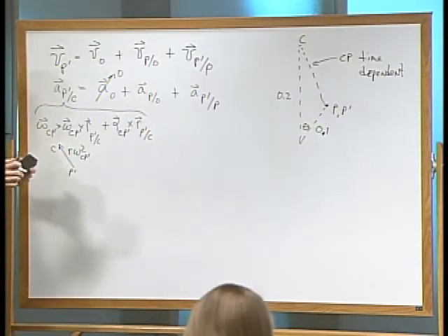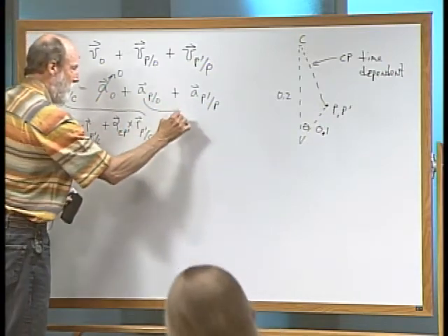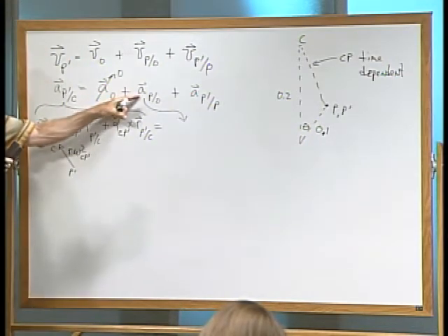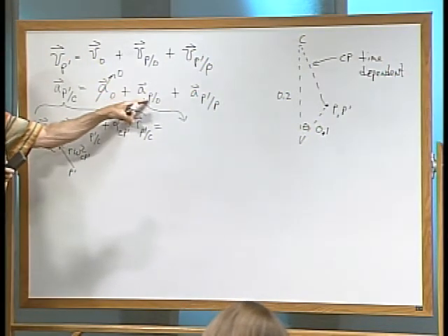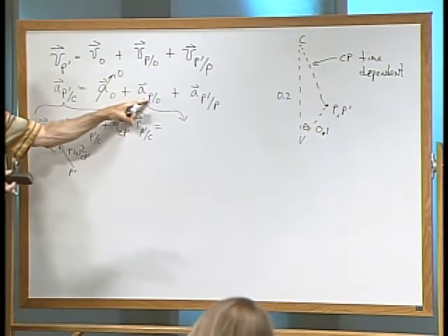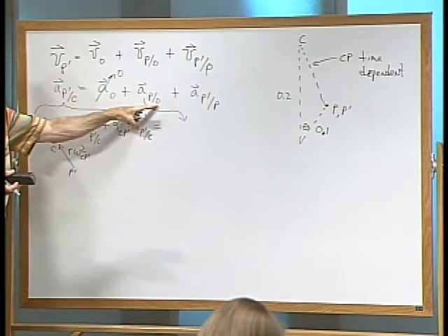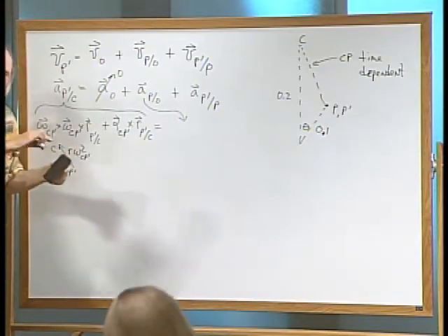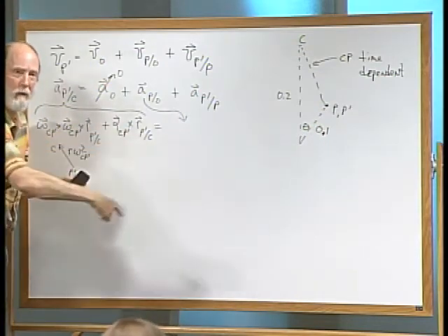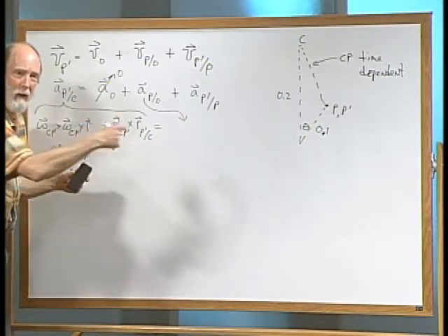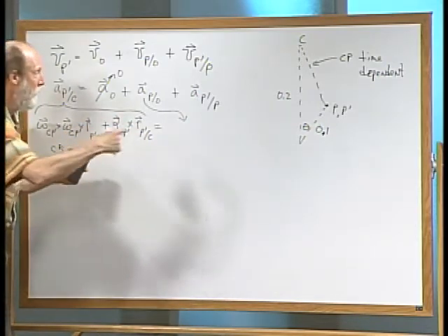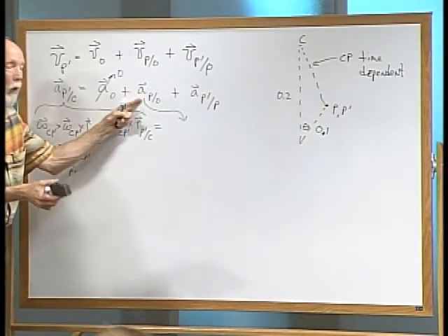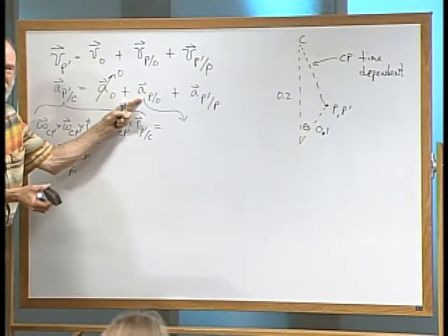Now, what about this term, P relative to O? The P is the pin on the circular wheel, relative to its center. How's the wheel rolling? At a constant rotational rate too, isn't it? Doesn't it have a constant omega as it's rolling along the ground there? Yeah, so all this is going to have is an omega cross r, or simply an r omega squared, right?